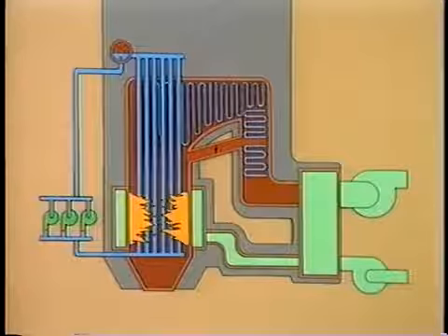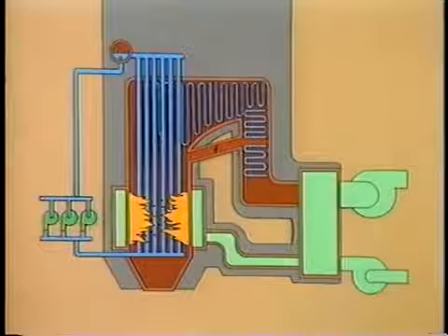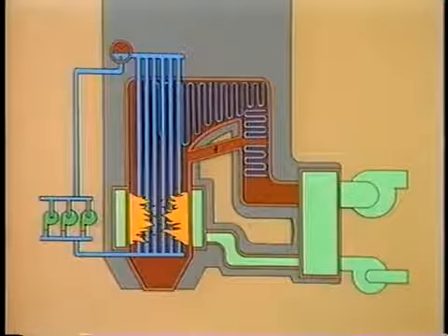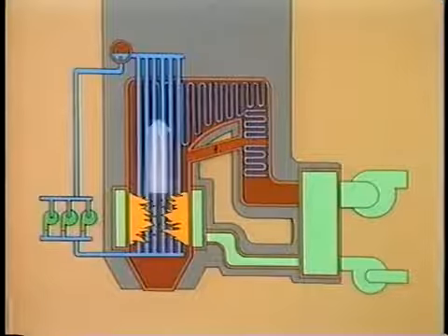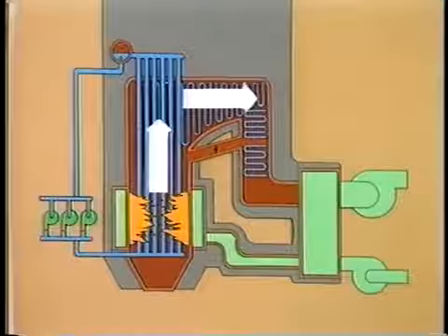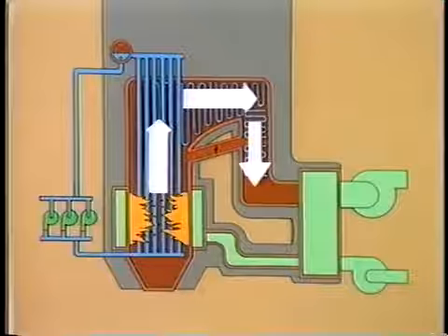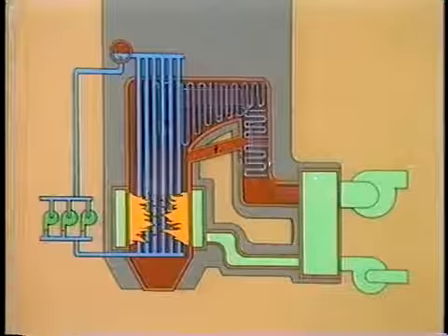To give you one example of how this unusual situation might occur, we'll use a boiler that has a gas bypass system for steam temperature control. As you learned earlier, under normal conditions, flue gas flows from the furnace area over the superheaters and reheater in this section of the boiler, over the economizer, and then through the air preheaters.